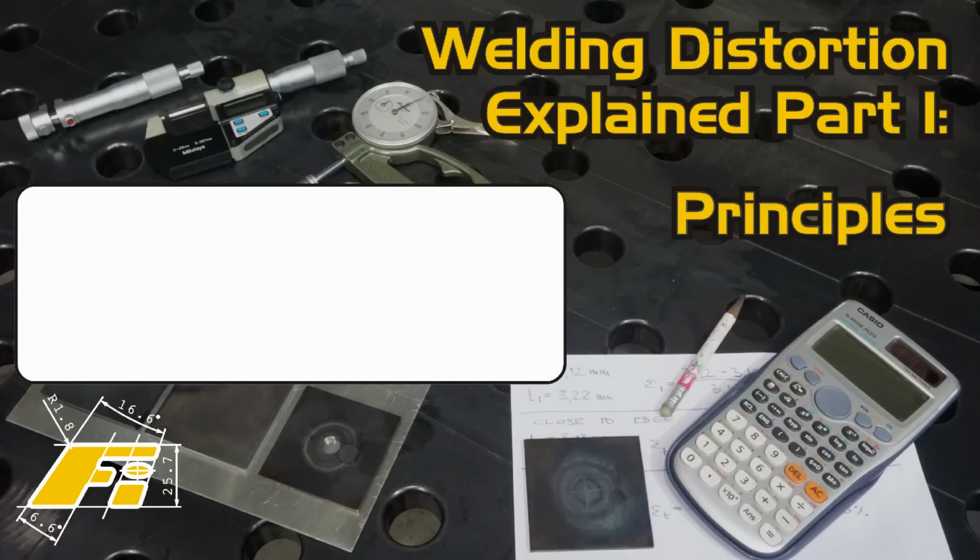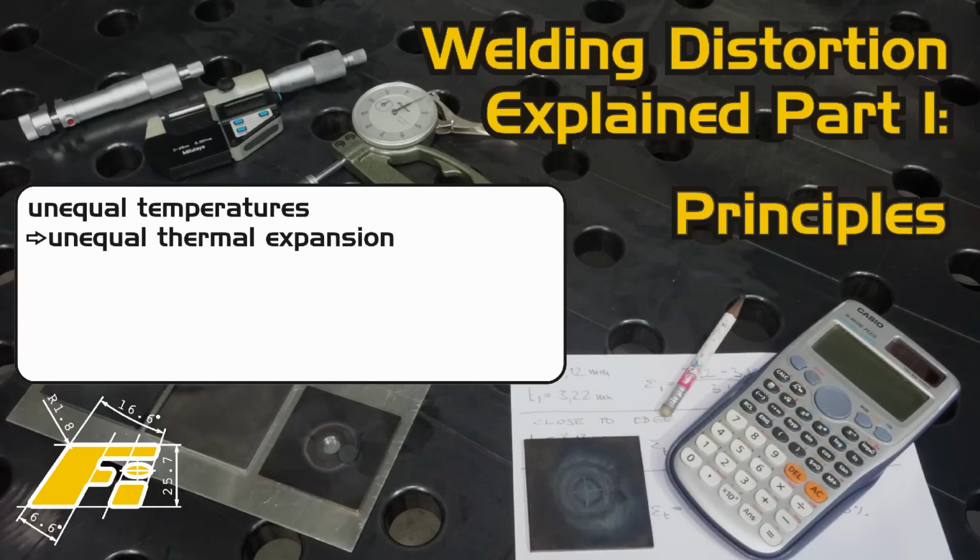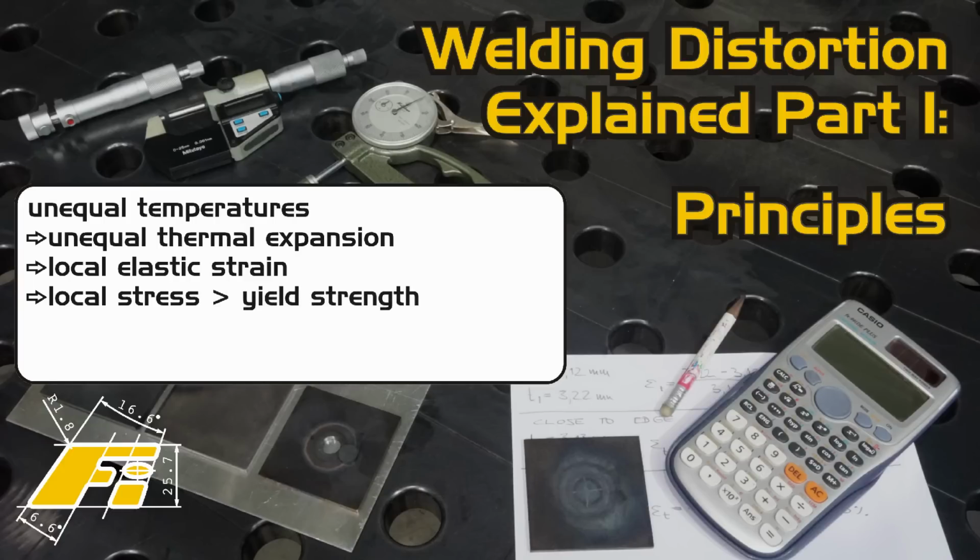The primary mechanism of welding distortion is driven by unequal temperatures in the workpiece. These cause unequal thermal expansion of it, which is balanced by local elastic strain, which in turn causes local stress. As soon as the local stresses reach a certain absolute value, that is the yield strength of the material, they give rise to local plastic, that is residual, deformation of the workpiece. The combined local residual deformations are the major part of our workpiece's welding distortion.